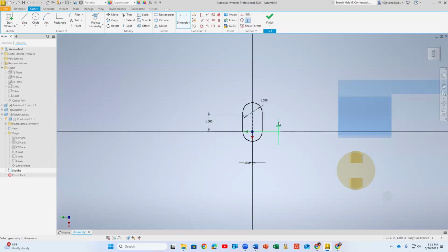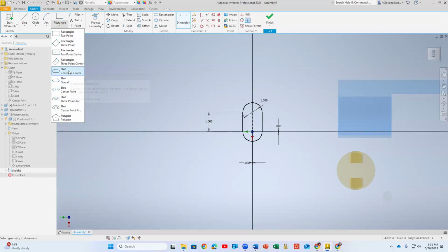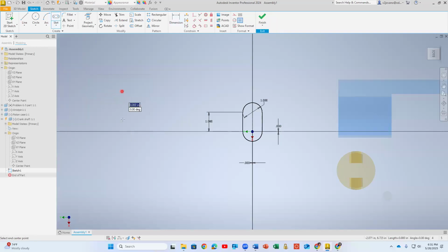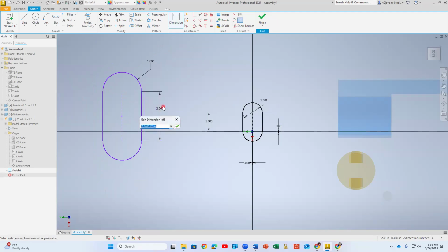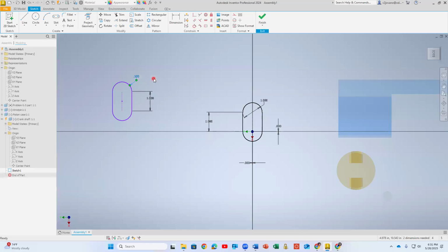So all of this trouble, all whatever I was showing you, could be easily done by using pre-made slot. You see, there are 3 different ways you can do slot. So if you pick any of them, it's just so simple, and we will get the same result. So you see, very simple steps by doing 1 and 1. Pick whatever, each one of these will work. And you see, this is radius. So if it's radius, it will be 0.5. But you see, these two are completely the same thing. But in this way, I show you a little bit more constraints other than just making slots.